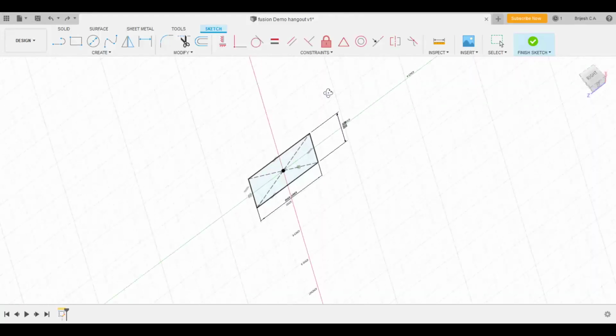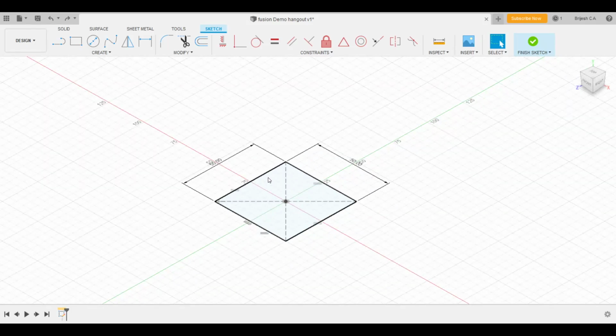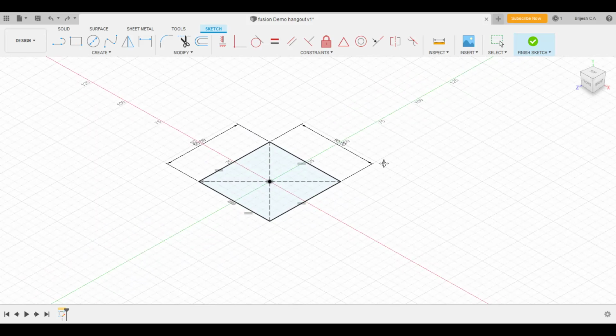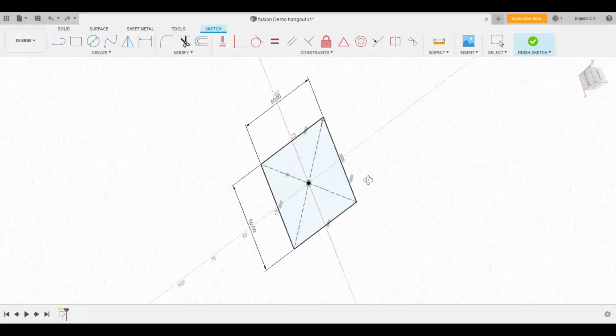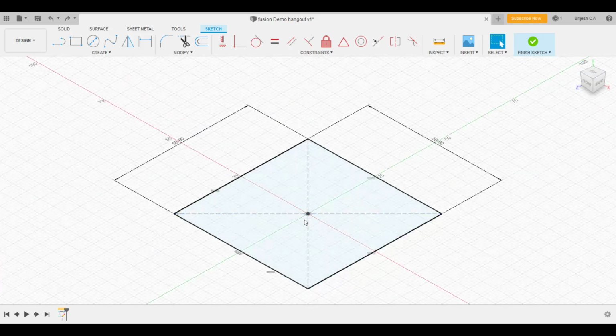Suppose I want to reset my view, I just click on this and it resets the view. Now this setting, whether you want to rotate it when you press the shift button or space button, is something you can configure on your own. You have keyboard shortcuts available that you can set, but by default, if you want to move it, you press the center scroll button and move it, and if you want to rotate it, you hold the shift button and then press the center scroll button. Okay, cool. I'm just going to click on the home option. It gives me the home view.